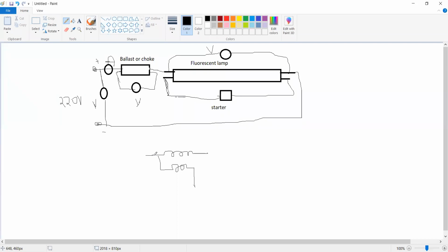This is the diagram of a wattmeter. It has 4 terminals, 1, 2, 3, and 4, and 2 coils. This one is the current coil, CC, and this one is the pressure coil, PC, or the voltage coil, to measure the voltage. The current coil should be connected in series, and the pressure coil should be connected in parallel. The terminals are M, COM meaning common, L for line, and V for voltage. These are the 4 terminals of a wattmeter.